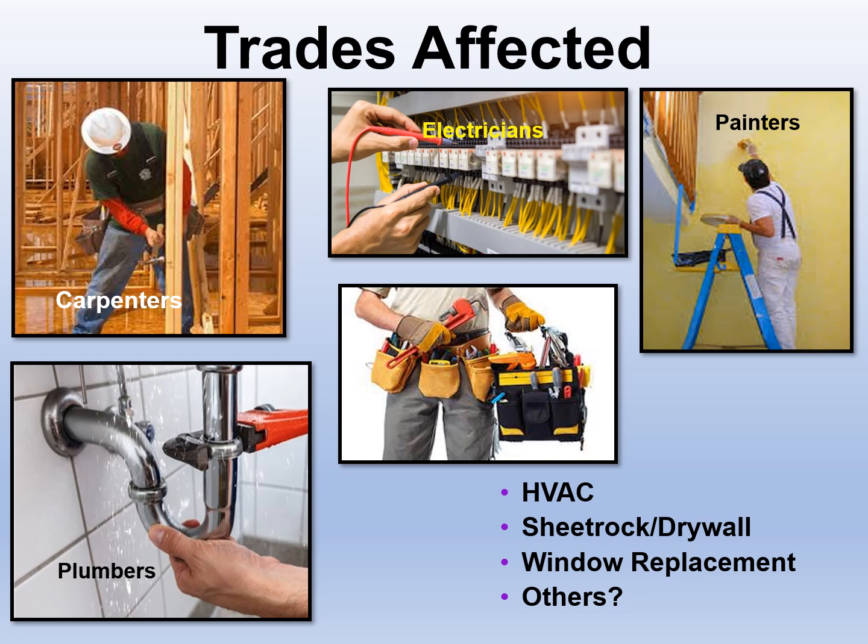In each instance, people engaged in these trades must take proper safety precautions, including wearing proper clothing and PPE, which is personal protective equipment. Also following the RRP rules of regulating the work area with poly and not allowing lead dust to migrate outside the work area, while constantly cleaning any debris that is being created.